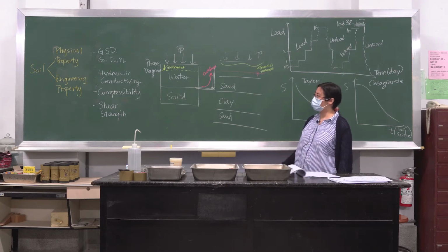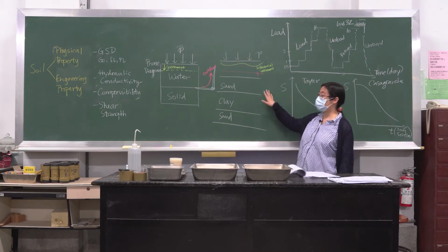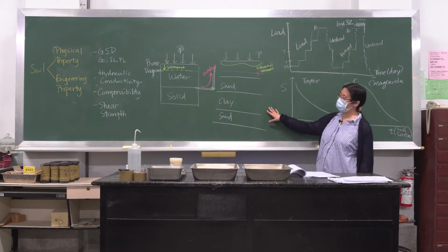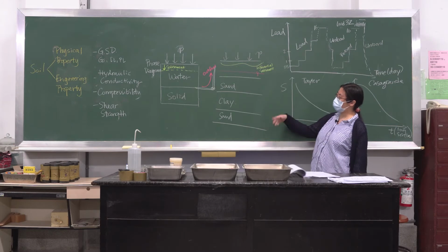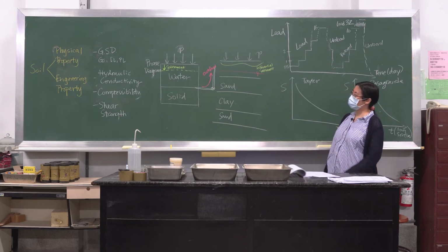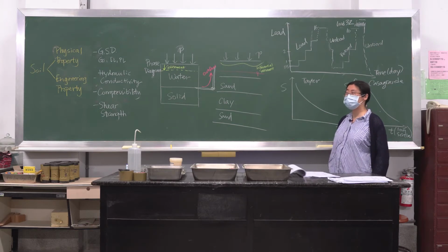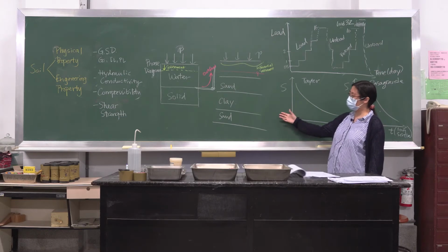As you remember from your class or from your lab, if you have sandy soil, the hydraulic conductivity is large, meaning that water pressure can dissipate very quickly. So you will expect the settlement to occur and end very quickly, maybe within hours or days. But for clay, if you remember from last week, the hydraulic conductivity is several orders less than that of sand. In real construction, it may take months, years, or even tens of years for the consolidation to complete.